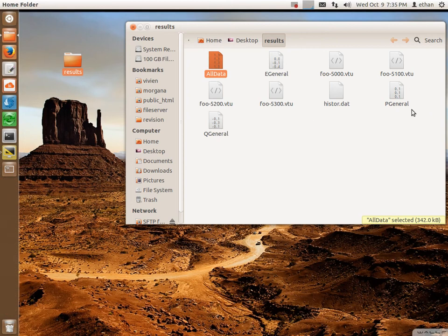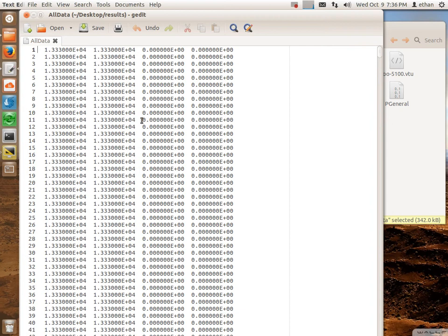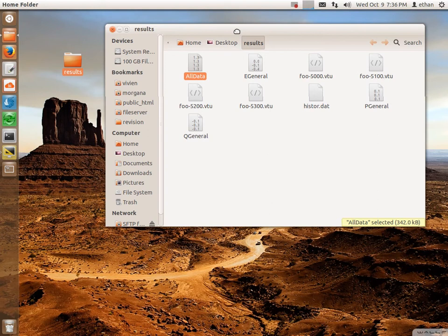The all data is generated by the genbc program. So this is essentially all the boundary condition stuff. But in our case, we didn't really do any calculations there, and that's why it's so boring here. But if you had a complicated network that you're solving for the 0D domain, then you could potentially have a lot of variables that you're solving, and then this file will provide you with the information of what the values are for those variables across the time steps.